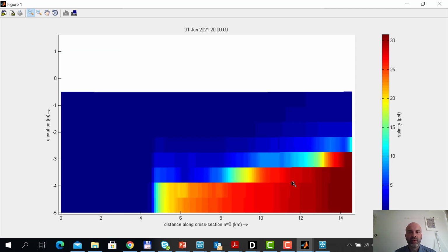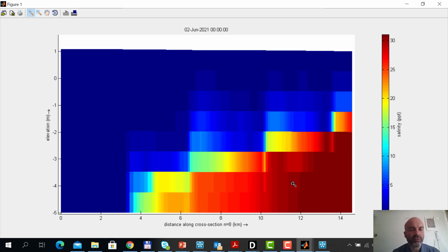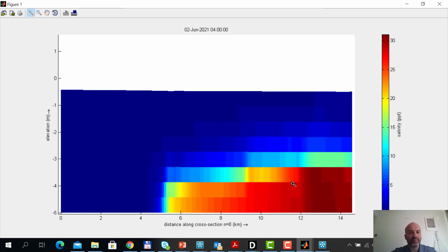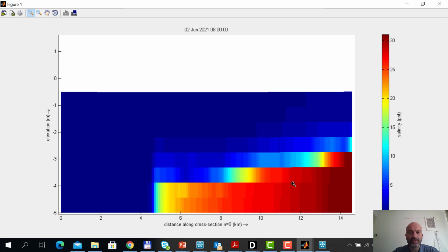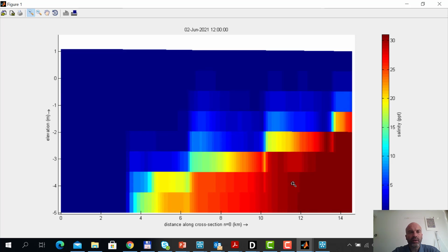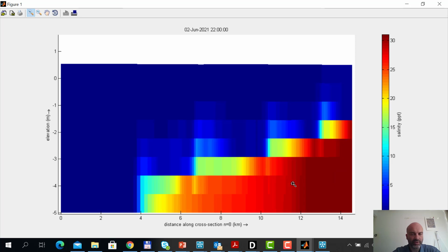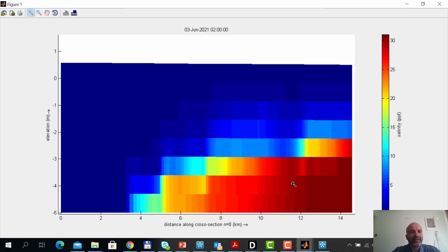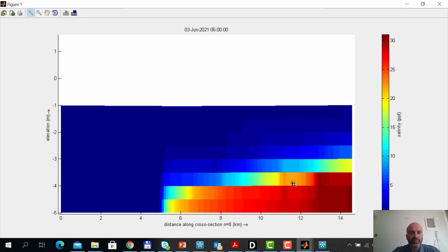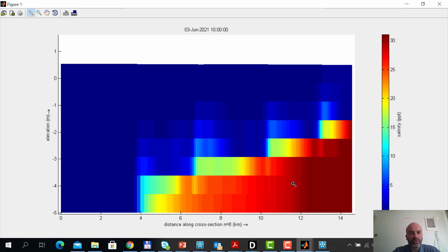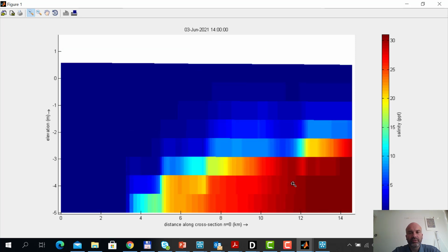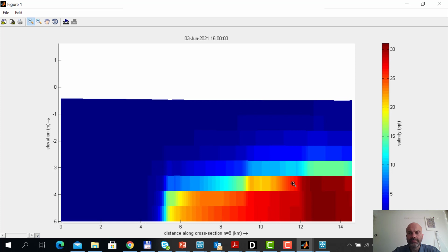But if I would increase the flow velocity at the riverside, that would wash out all the salt. And at the same time, if I would increase the tidal prism, or the tidal amplitude, that would put more pressure on the salt intrusion, with more salt intrusion length as a consequence.